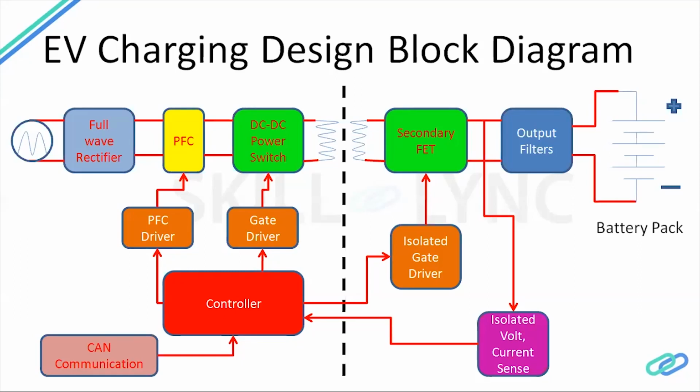Fine. So what steps do you need to do first? First of all, your voltage is AC, right? So you have to convert that AC voltage into DC voltage through a rectifier, basically a full wave diode rectifier.